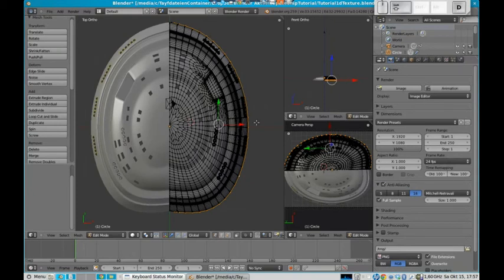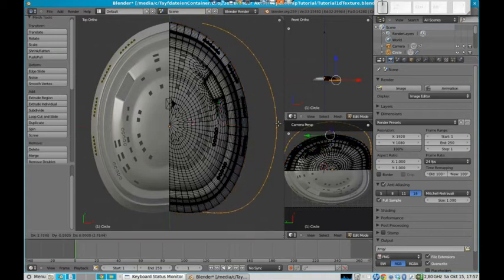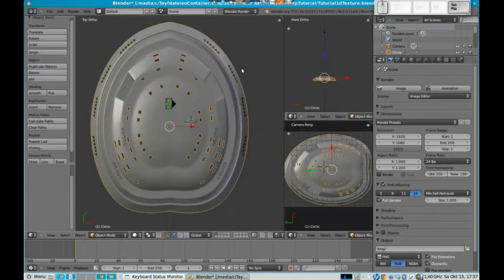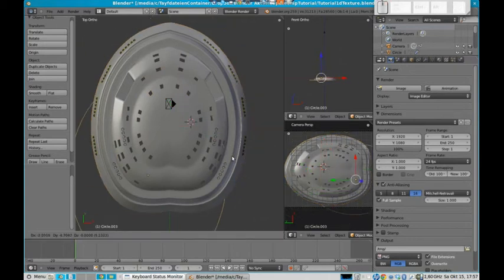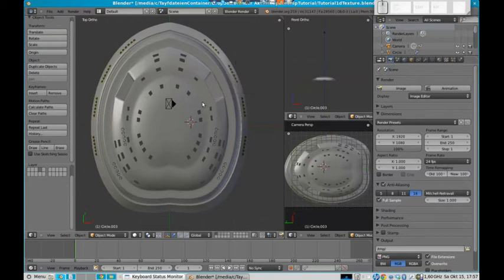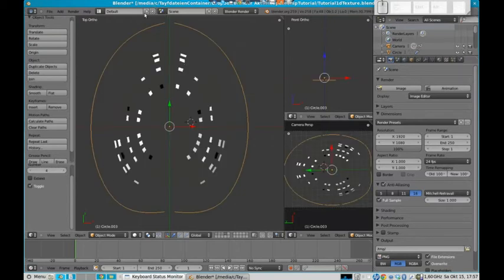Let's copy this one. So I have copied this and I press the escape key so that they will be where they were before I moved them, and separate them by pressing P again and then the selection key. Now go back to object mode and try to select just this line here. Genau. And I was able to do so. Why am I doing that? I am doing that to be able to move that to layer 4 now, where our windows are, and now I go to layer 4 and I see the outline of my ship again.